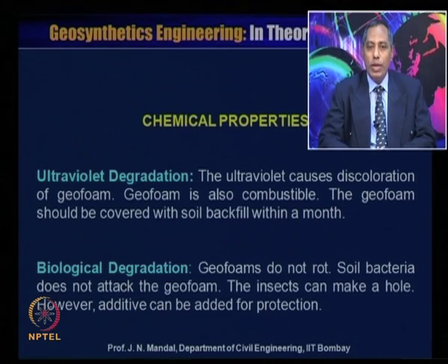So, one has to take care. Even in the case of geotextile material, you know that you cannot keep it open for many days. So, you ought to cover the geofoam material within a month in order to protect it from sunlight. Otherwise, all the properties of the geofoam material will deteriorate or reduce.